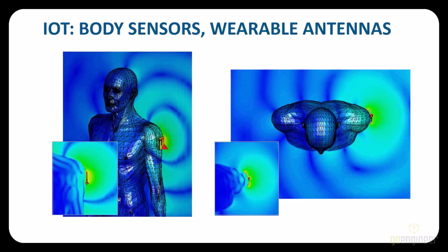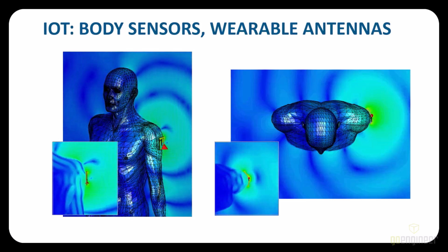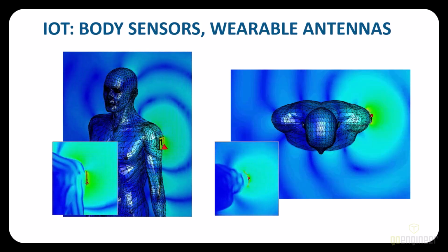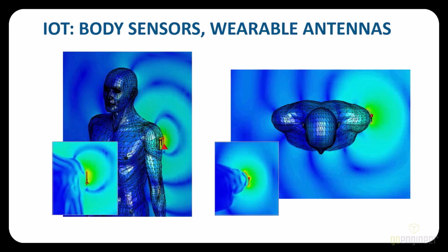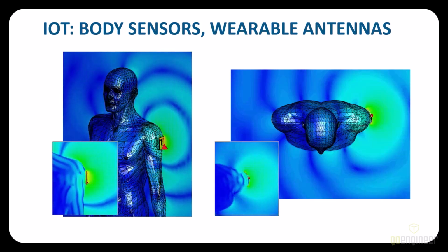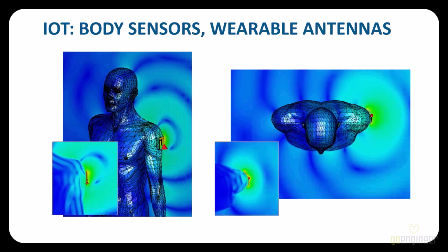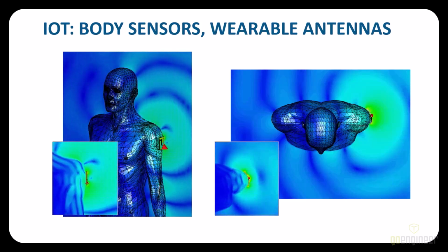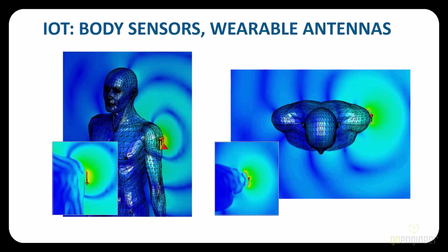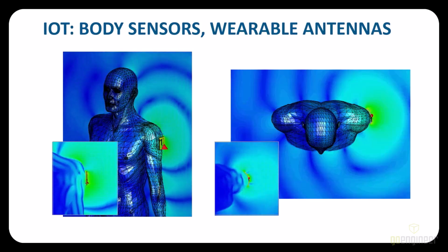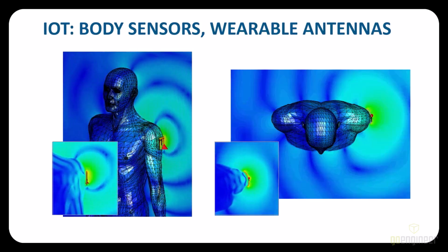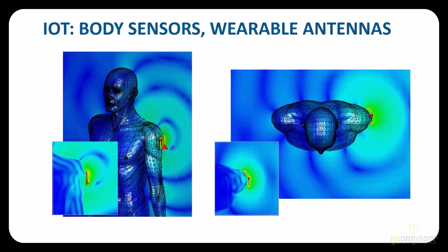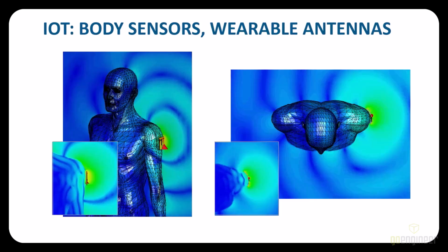It is also nice to see how fields propagate inside the body with high permittivity and hence shorter wavelengths compared to free space. These penetrating fields cause power losses in the tissues that form the basis of SAR evaluation and potential heating. Some of the cases we can analyze are where to position the antenna in order to achieve the best far field pattern without causing high power losses, and whether a single antenna would be sufficient to provide a